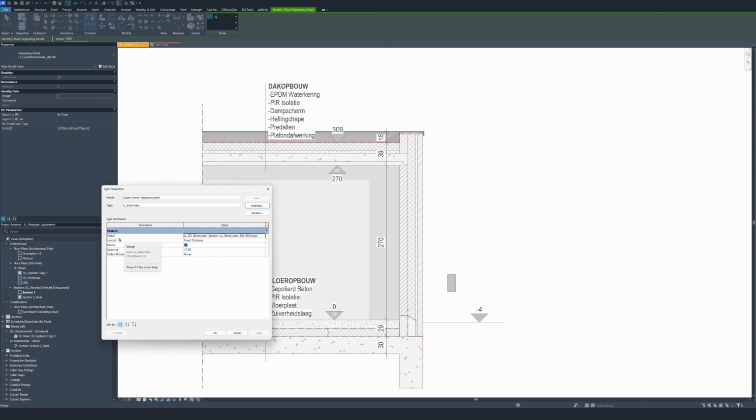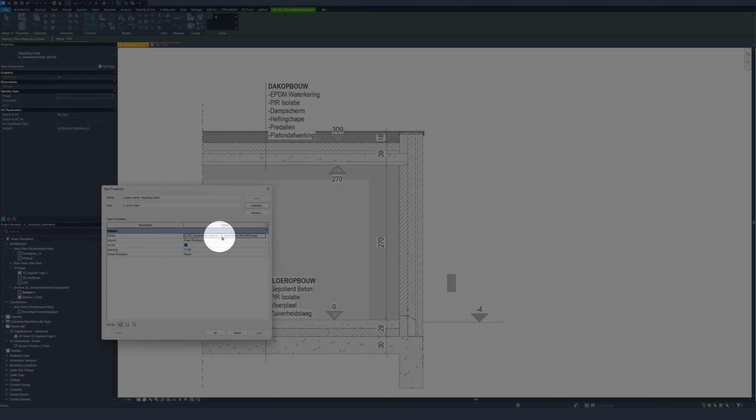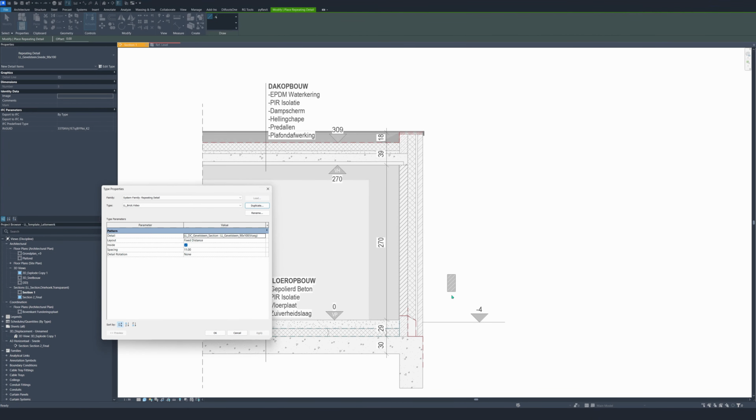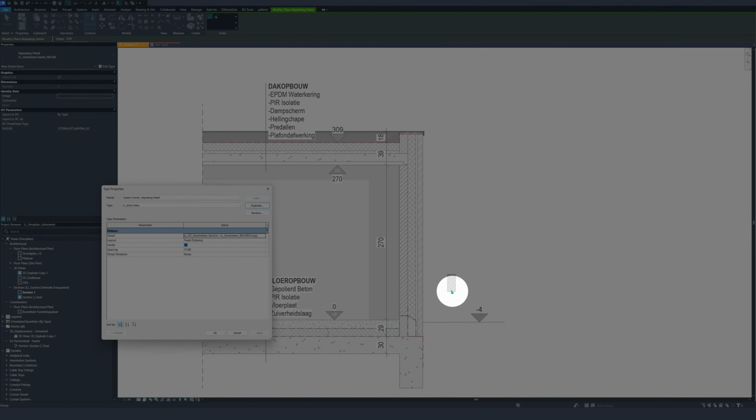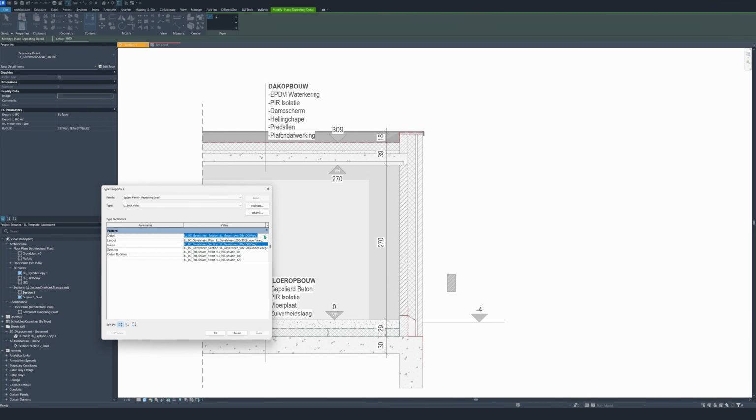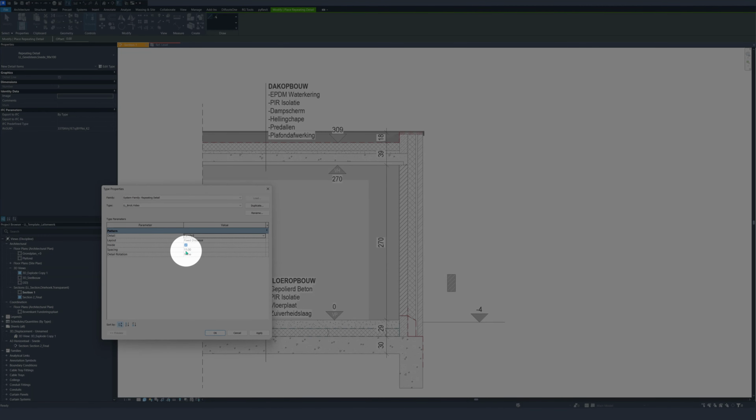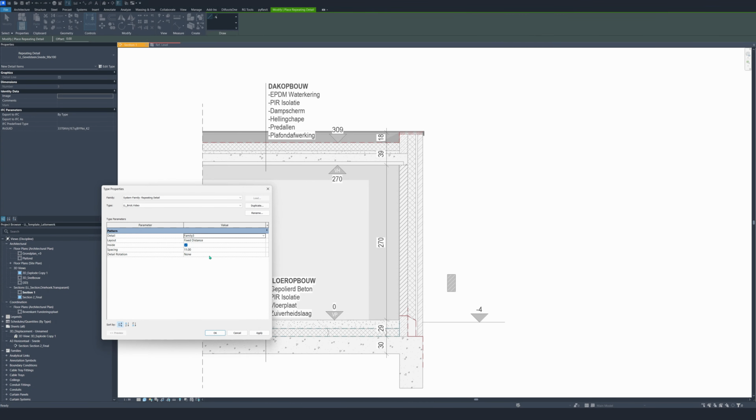The second thing that we need to do, and of course you need to remember the name of the family. Right here you see detail and a name. Well, you need to know the name of this family that we made, so we're gonna search for it, and normally it's family tree. Voila, right here, family tree. And then layout, you just of course do a fixed distance, because the fixed distance will be 11, but we know that it's 30, so we need to change it to 30. Then tab key, voila,